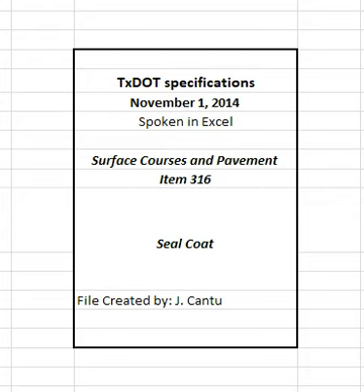4.6 Surface preparation. Remove existing raised pavement markers. Repair any damage incurred by removal as directed. Remove dirt, dust, or other harmful material before sealing. When shown on the plans, remove vegetation and blade pavement edges. When directed, apply a tack coat before applying the hot asphalt rubber treatment on an existing wearing surface in accordance with section 340.2.5, tack coat.